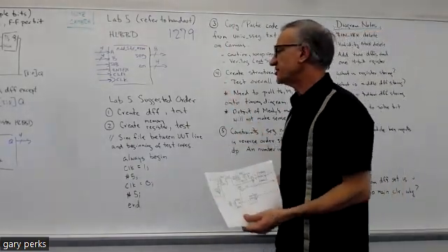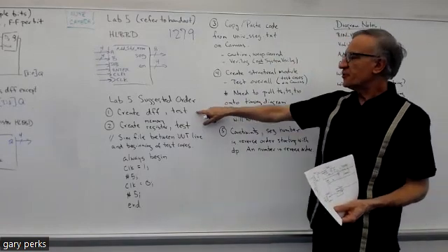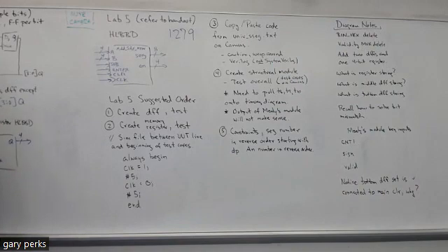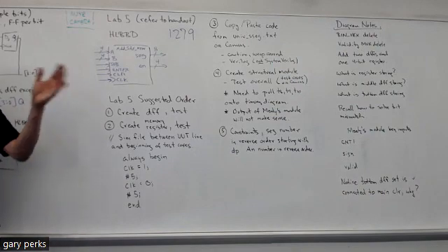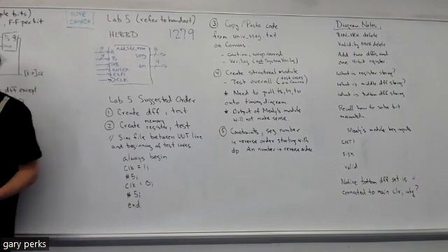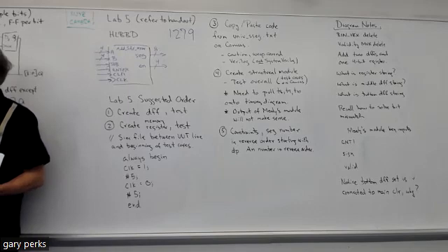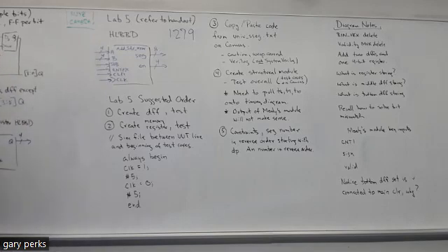All right, so this is my suggested order for Lab 5. The first thing I suggest that you do is create the D flip-flop, right? Again, you got most of the design source code right there. Then test it. You'll need a sim file. Can you think of test cases that you would need to test this? Give me a test case. What do you want to make sure works on this? What is a D flip-flop supposed to do? Say it again. Right, store a bit.